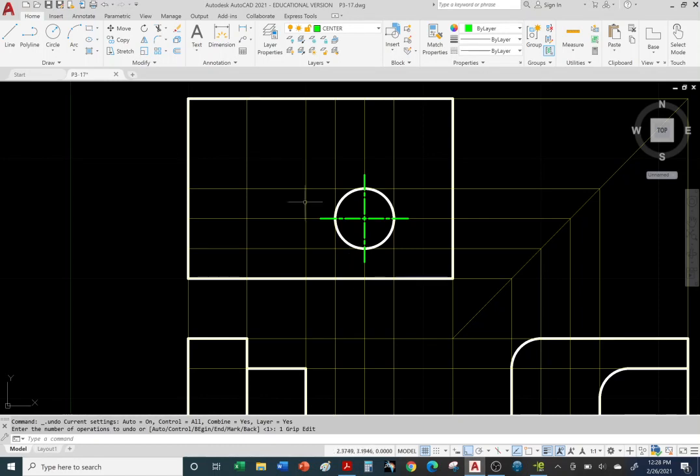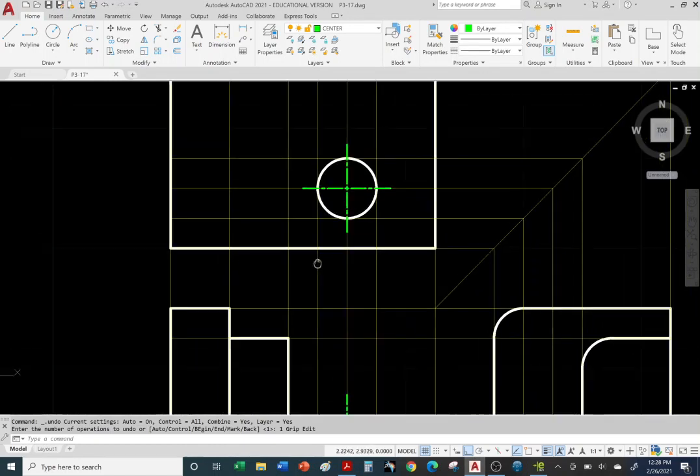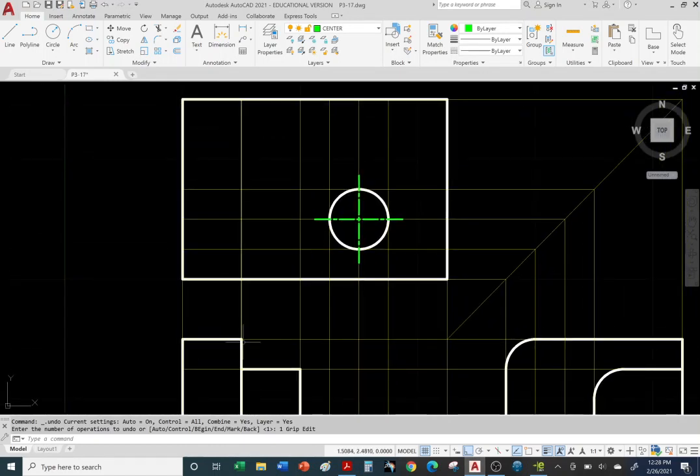let's go back to AutoCAD. Okay, so let's go ahead and complete the top view. Okay, so from this corner here, from the front view, we're going to draw a line straight up, right? Okay, so let's go ahead and turn on Object Snap. And let's go to the white visible object layer and use the line command.